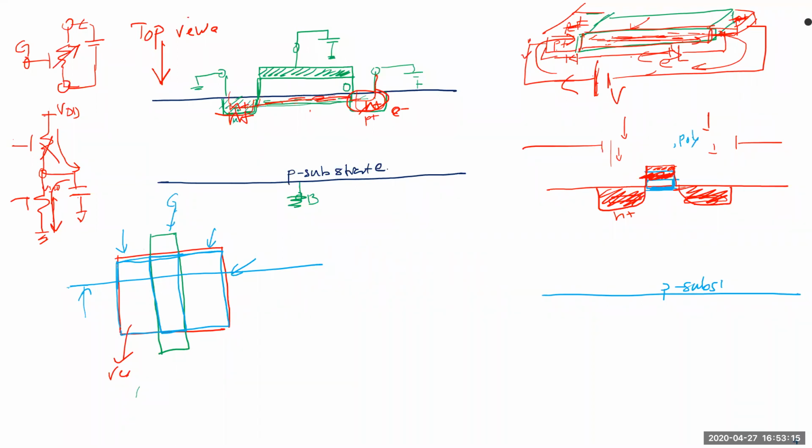Because of that, they put polycrystalline silicon, and when they bombard it, automatically it avoids putting N plus in the channel area because the poly and the oxide block it. But at the same time, it actually dopes this. And that's the way you get your N plus on your source and drain. You also get N plus in the ND.